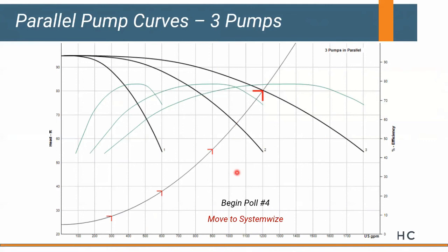It just means that you can't run 1 pump at 60 hertz. So further evaluation would be warranted if everything else about that selection looked good. That was all I was going to comment on.